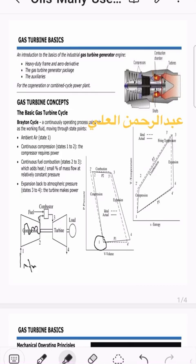Then the air goes to the combustor. Here is the second stage. From the second stage to the third stage, here we call it the combustion side. What is happening here? The air is going to the combustor side, and we add some fuel to combust the air, which produces a very high temperature. Then all this hot, combusted air goes to the turbine.